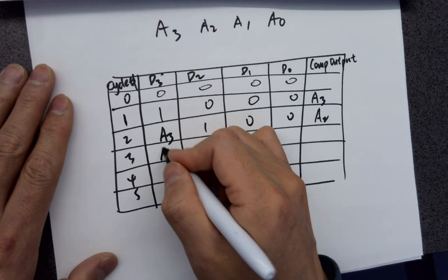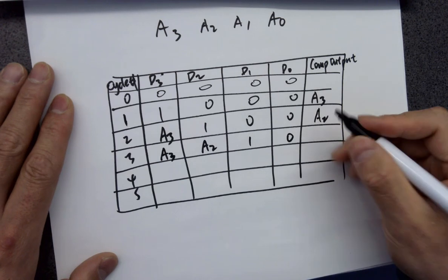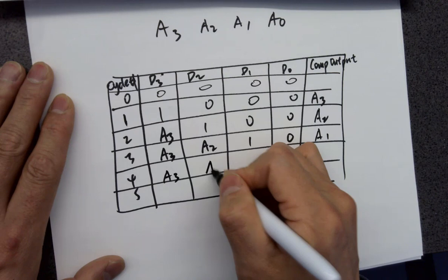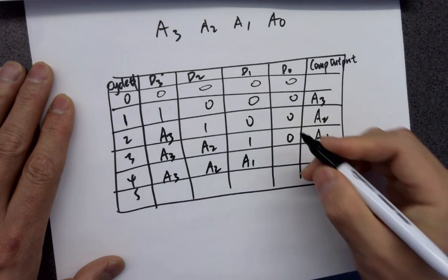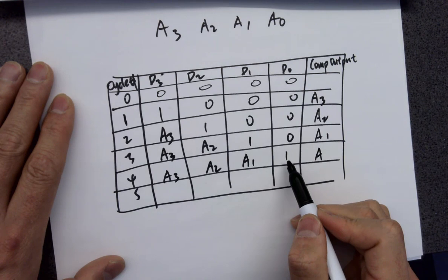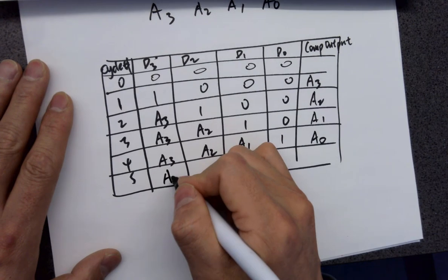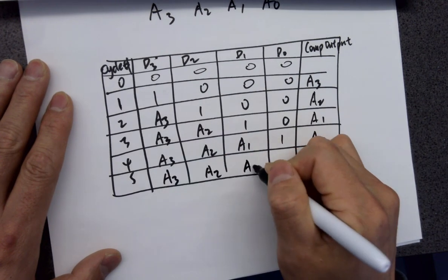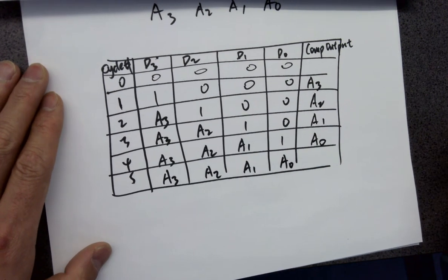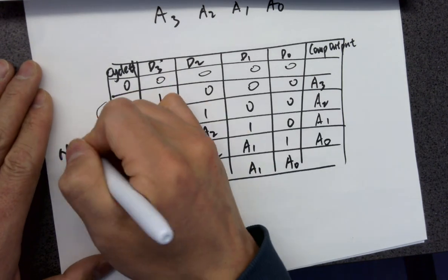And that A2 is being plugged in here. And this result is giving us A1. And A1 is being plugged in here. And this, compared to the comparator's non-inverting terminal, is giving us A0. And eventually you are getting this. So for a 4-bit ADC you need 5 cycles, which is n plus 1 cycles.